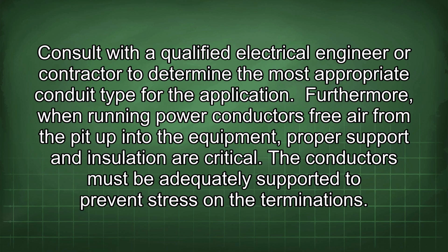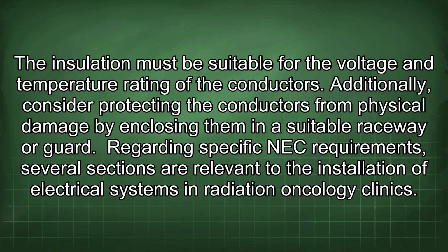Furthermore, when running power conductors free air from the pit up into the equipment, proper support and insulation are critical. The conductors must be adequately supported to prevent stress on the terminations. The insulation must be suitable for the voltage and temperature rating of the conductors. Additionally, consider protecting the conductors from physical damage by enclosing them in a suitable raceway or guard.